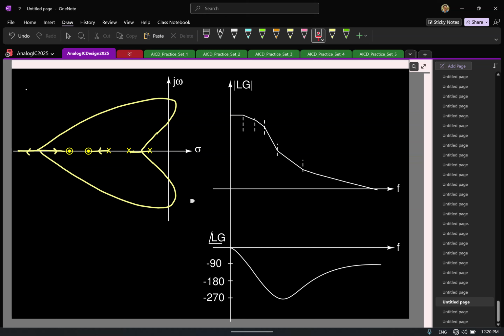Okay, so now let's actually look at this DC gain A0 prime. Remember, I start with very small values of DC gain, the poles are here. As I keep increasing, they kind of branch out like this, and at some particular value, the poles are lying here. Correct? At A0 equal to A0 prime, what can you say about the closed loop poles? I mean, forget about marginally stable. What can you say about the closed loop poles?